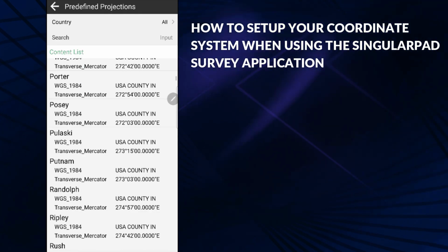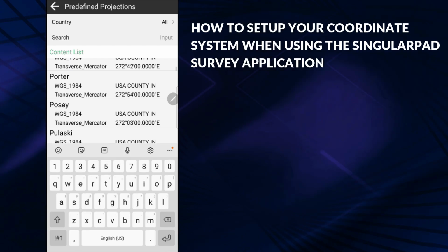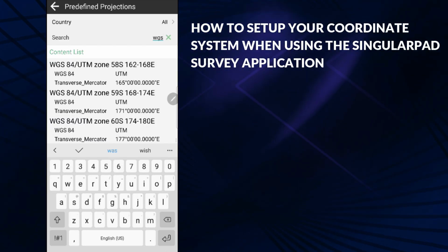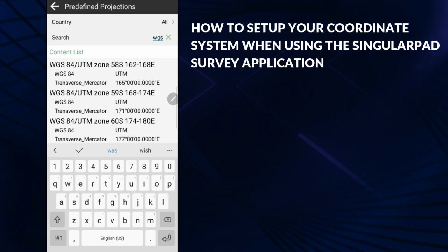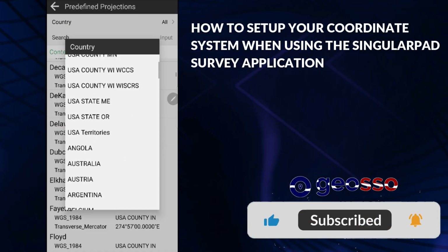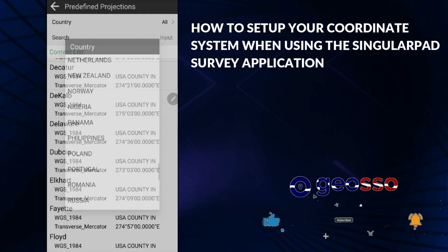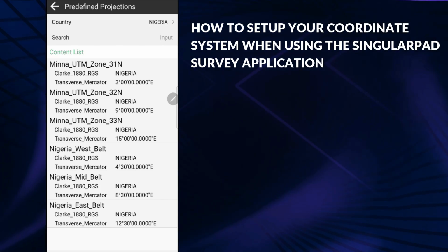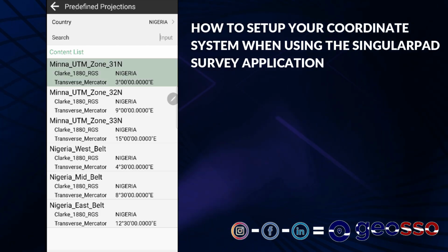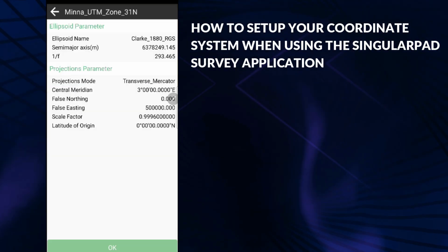If you want to search directly, you can go to the search and input. Let's say we are looking for WGS. So this is WGS, and you select your zone in the WGS coordinate system. But for now we are using Nigeria, so we'll go back to Nigeria, and under Nigeria we are using UTM zone 31. That is our zone. So we'll select that and we'll go to details.